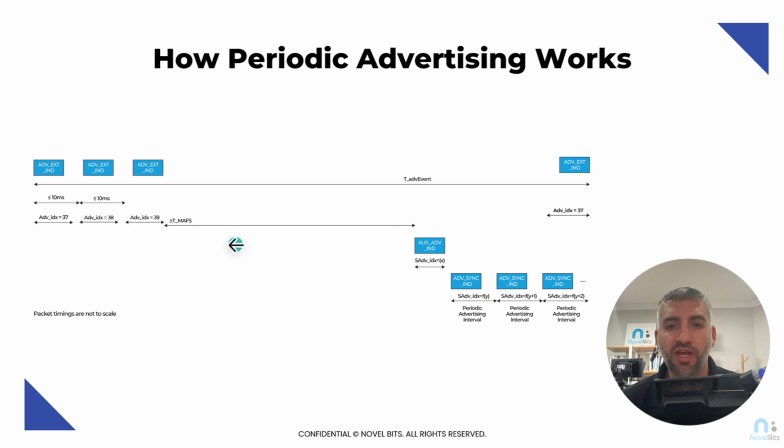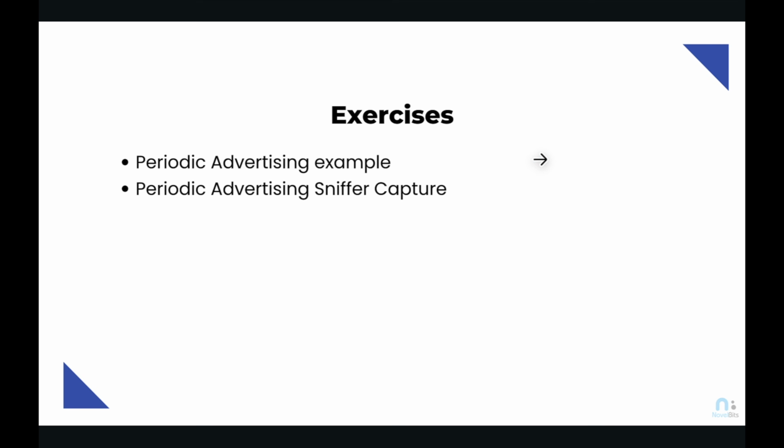The next time, if a device goes through this sequence and finds this, it will then not need to go back to scanning for these. It will just continue to wake up at an exact time, the periodic advertising interval, and be able to find these packets and read the data in them. If a new device comes in, then it will have to go through that sequence at least once in order to find these.